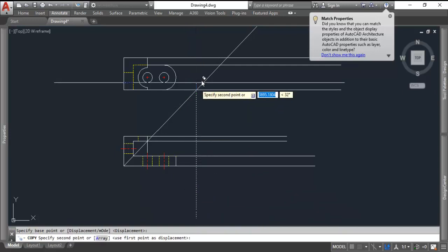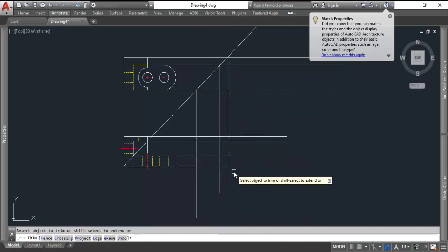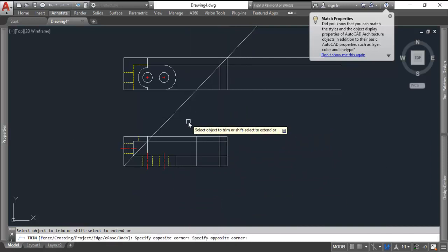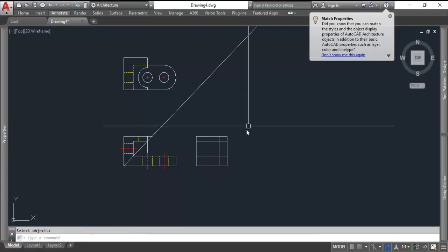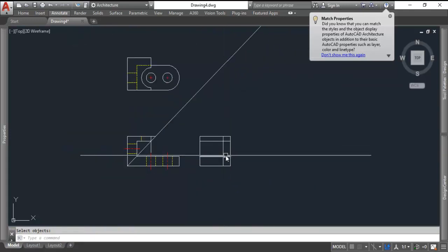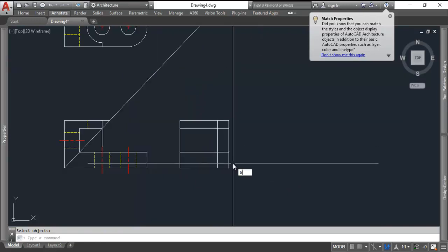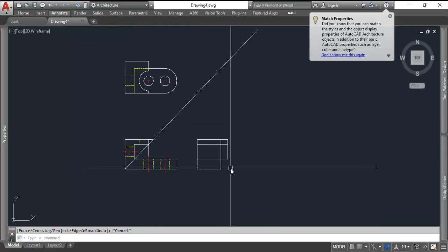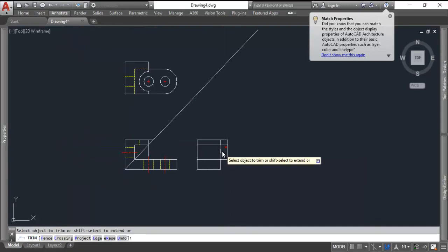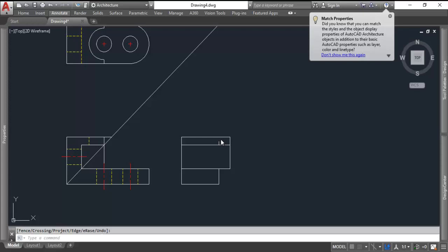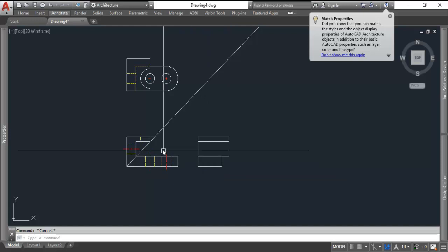So just start with your major lines, copy them in there, and then we're going to trim away what's extra, like so. We can get rid of these lines now. So looking just at our shape, we have to make a decision, and it appears to me like this top block, since I can see a hidden line, is hanging over. So I think we should look kind of like that. Here, I'm going to remove that for now and that for now. So we'll start with what looks like that, and then we're going to add to it.